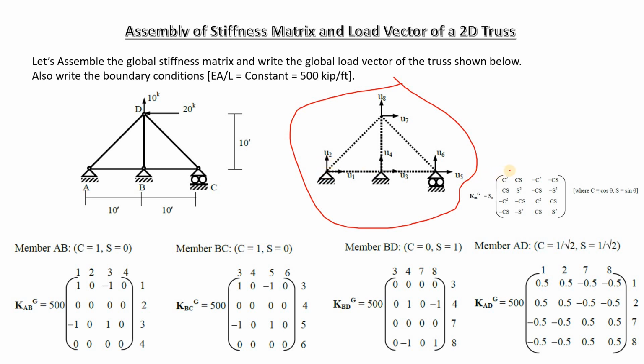And remember that always the horizontal displacement is the first displacement and the vertical displacement is the second displacement, because that is how we formulated the matrix. Remember, 1, 2, 3, 4, where 1 was the horizontal displacement, 2 was the vertical displacement, 3 was the horizontal displacement, and 4 was the vertical displacement. Remember that? We have done that from the local axis matrix formulation, right? So that is how we have to calculate things.